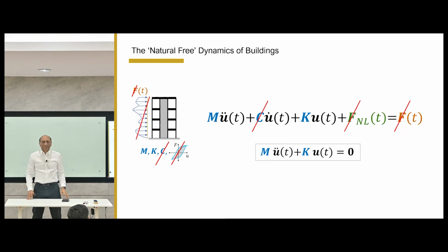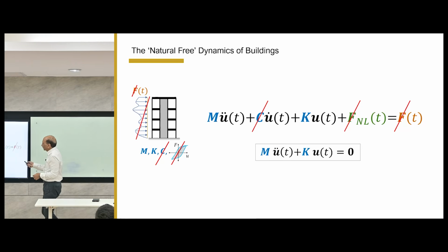That vector is the one that we are going to use. So there are two things now: the natural frequency will come out of this, and a mode shape will come out of this, right? The mode shape is the vector of displacements, and the frequency is the number or multiplier that will result in this being 0. It's a scaling factor for those displacements that, once multiplied, will give us this equation equal to 0, right? So that's the math behind that, without going into the math.